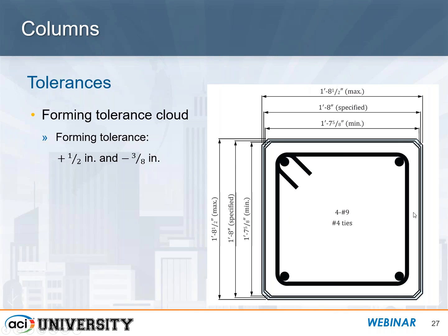Providing more reinforcement longitudinally than what you need is only going to complicate matters in terms of constructability, especially when you consider your placement tolerances and your forming tolerances. Things can get really crowded very quickly if you put in a lot of extra bars that you can satisfy with a smaller number of larger bars.